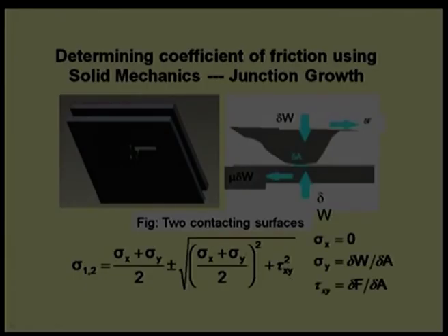If I simplify, assume there is a normal load only in y direction and in x direction there is no force, then sigma x will be 0, sigma y will be the normal force divided by the projected area, while shear stress will be the friction force divided by the contact area. These are simple expressions. Difficult expressions can be achieved, but initially we want to find, with this approximate relation, something which can give results close to the experimental results.